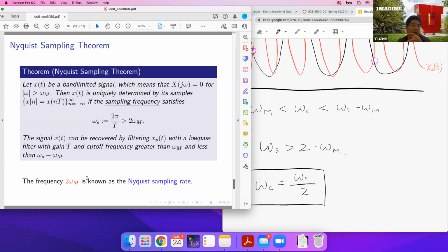And in the reconstruction process, correspondingly, we are looking at low pass filtering, because low pass filtering exactly works on a continuous band. So in the forward process, we are looking at a band limited signal, and in the backward process, we recover the signal by low pass filtering.